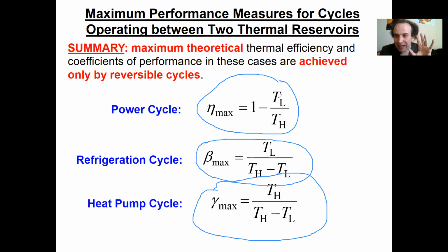The formulas are exactly like we had for the power cycle. Instead of Q, I write T here. And you understand why? Because remember how Kelvin defined it: at absolute zero, all cycles are reversible, and the scale was defined when Q is proportional to T. Do you understand this? So that is the main formula.